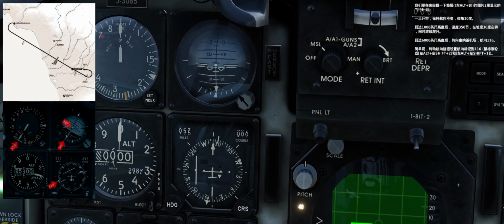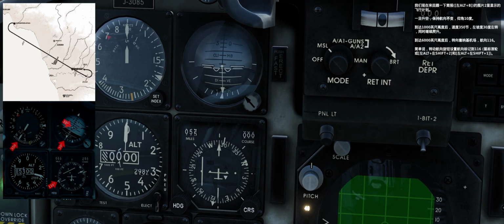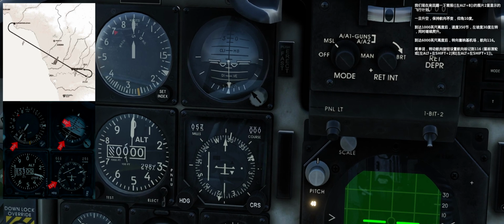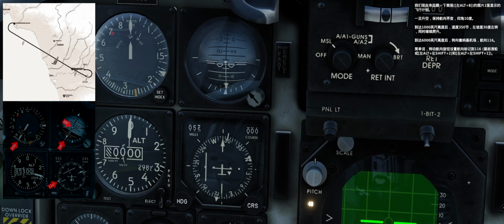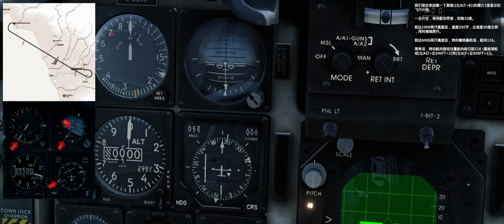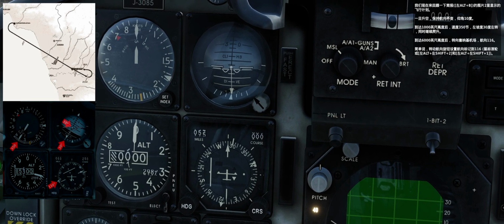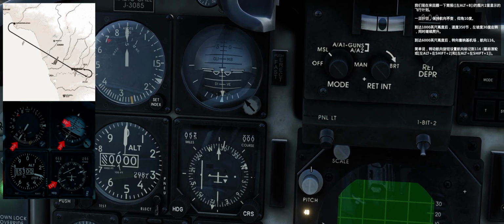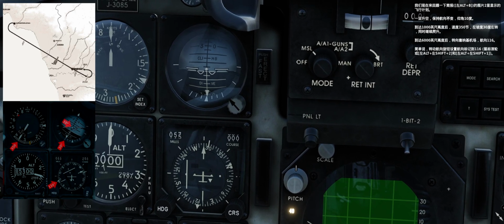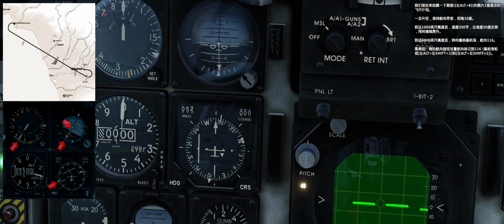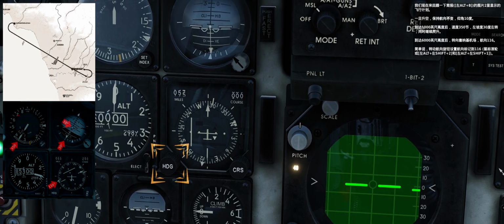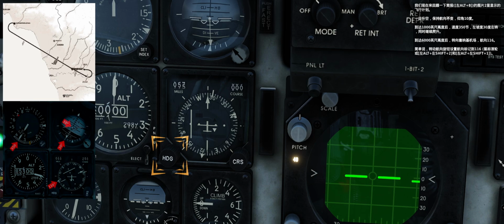We will now review the flight plan, which is shown as Figure 2 in the briefing, left Alt plus B. Once airborne, follow the takeoff course with 10 degrees pitch. At an altitude of 1,000 feet, perform a left turn with a 30-degree bank angle at a speed of 350 knots while simultaneously climbing. Figure 3. At an altitude of 6,000 feet, turn towards Senaki-Kohli airfield on a course of 116 degrees.